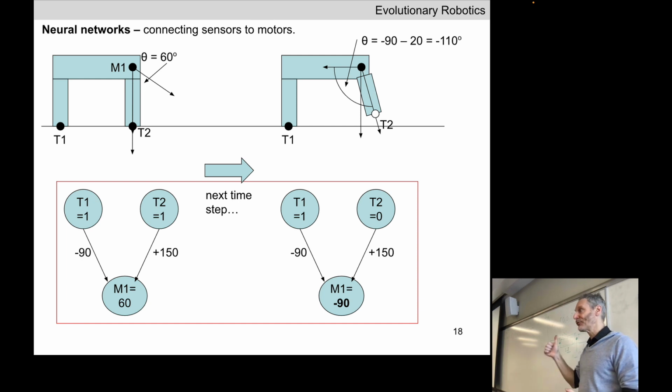Absolutely. Remember, one of the forces that can act on links is friction. If they're all rotating horizontally, they're all staying in contact with the ground and they're grinding on the ground. If each of these links has a touch sensor inside of them, those touch sensors are always one. The robot is also kind of blinded. It can't tell when it moves whether there's been a change in its environment. So again, you can play around with this. This is probably not a very good design.